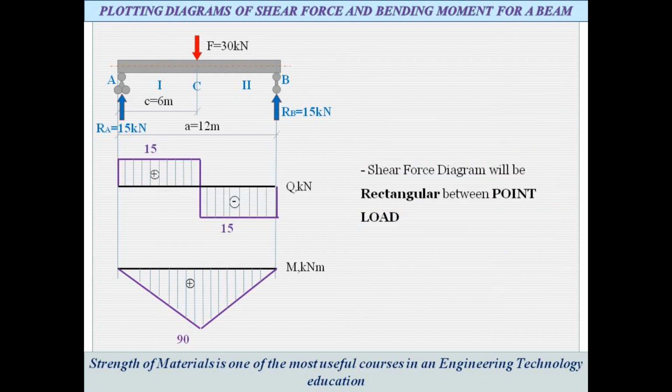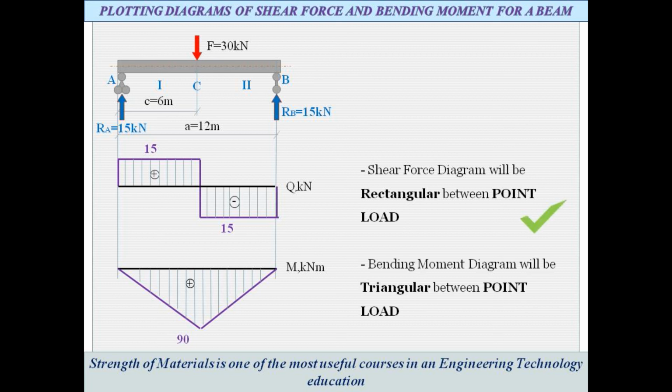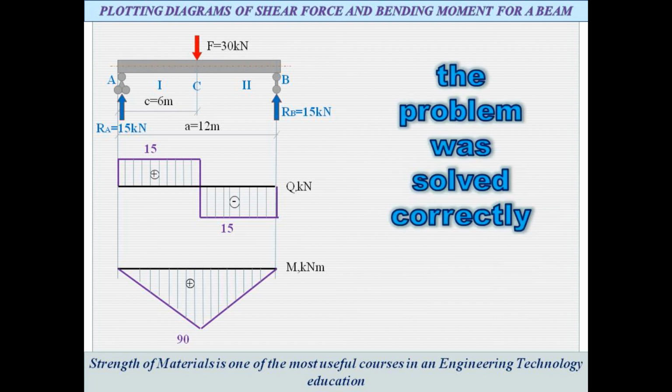After all, you must analyze and check your diagrams. The shear force diagram will be a rectangle between point loads. The bending moment diagram will be a triangle between point loads. The problem was solved correctly.